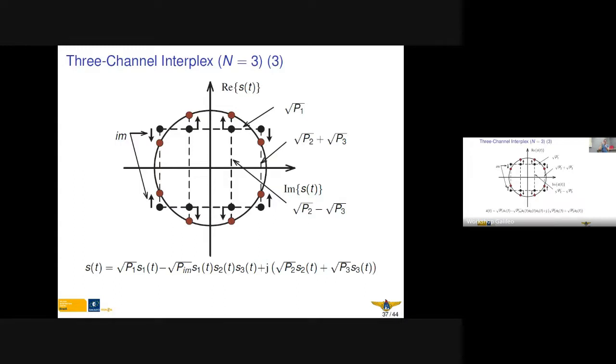The maximum of the signal power is then equivalent to the average of the absolute value squared of the signal. So the intermodulation product introduces a kind of pre-distortion of the superposition of the signals such that a constant envelope can be realized.